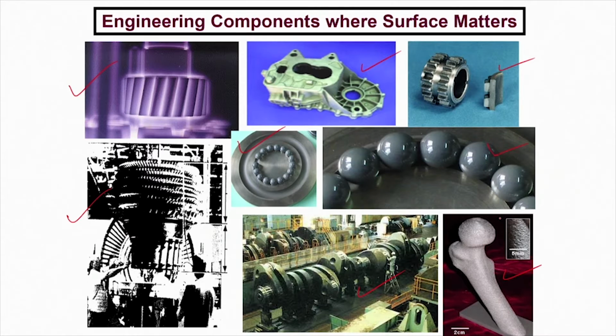Yet there is one thing in common, that all these components, when they undergo failure, the failure usually initiates from the surface, and that is purely because of the fact that the intensity of stress interaction with the surface is maximum, and also the environmental effect intensity at the surface is again higher than any other parts.